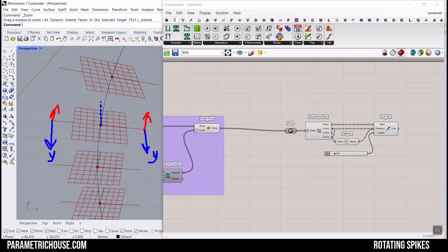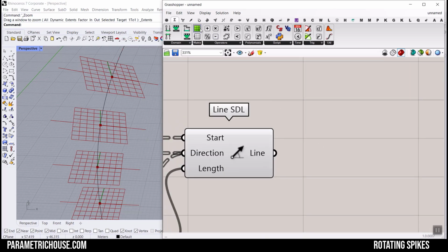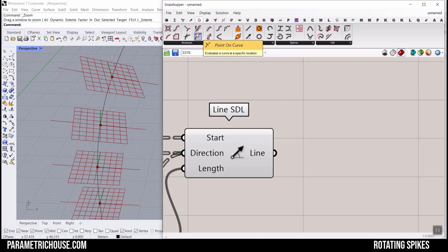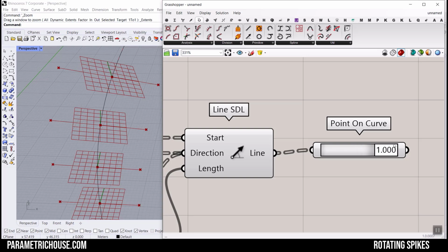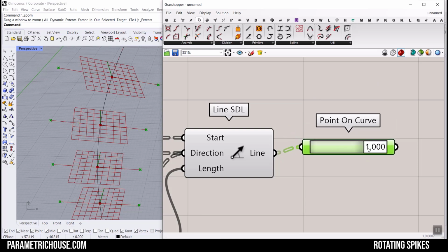If I rotate it around the Z direction, for example, I rotate this 10 degrees inward, so it's going to go inside, and 10 degrees inwards to here. It's going to have 2 handles inside. Okay, if we have it minus 10, it's going to go outside, so we have to fix that. Let's go here. I'm going to go to the curve, use this point on curve tool, and pick up the start and the end. Actually, we don't need the start, we just need the end, right?